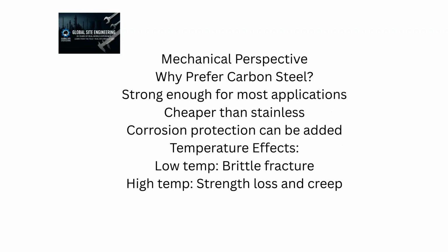Mechanical perspective. Why is carbon steel so widely used? It's strong enough, cost-effective, and corrosion can be managed externally. However, its mechanical properties do change with temperature. At low temperatures, it can become brittle. At high temperatures, it weakens, which can be dangerous in long-term service.